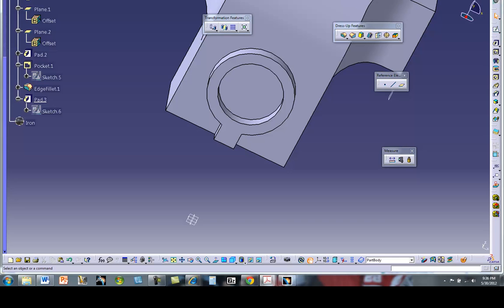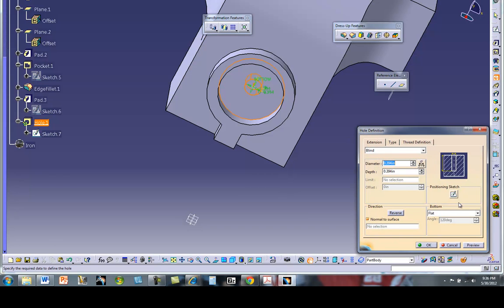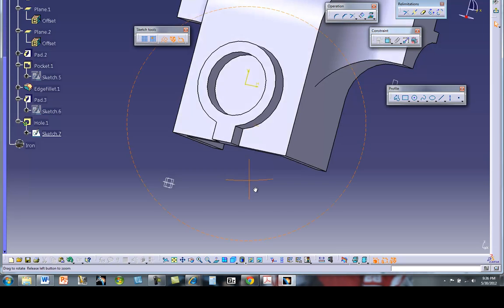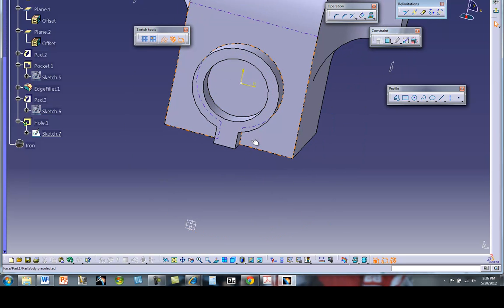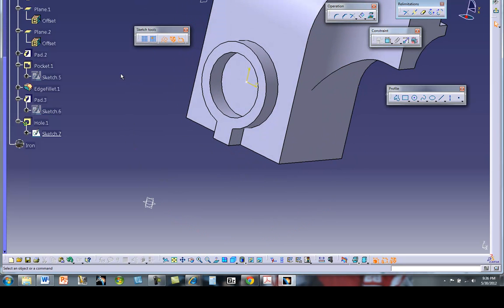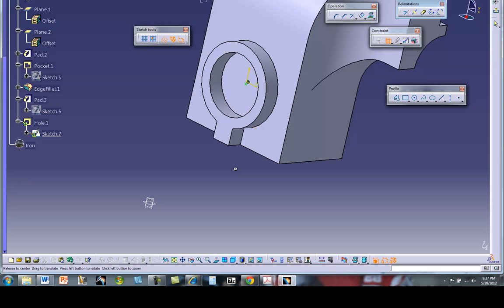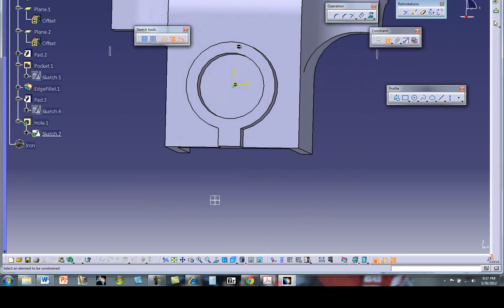Okay, on page 129. So again, hole command, going from here, placing this surface. Then you want to get in a position to sketch. Now notice that that part right here shows the center point of the hole is white. So if I come over here and grab that point, and I grab the axis of that cylinder by its surface, then I can make this coincident. So now it's always going to follow the center of wherever this cylinder goes.